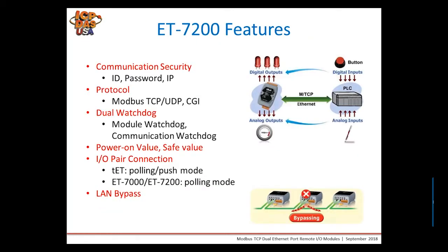This reduces the number of Ethernet ports required and Ethernet switches. So in this configuration on the bottom, the PLC or controller connects to one port of Ethernet switch, and a single port is used for the slave devices, which are daisy chained onto each other. Versus the top configuration where each individual slave device and master device must have its own Ethernet port, and because this illustration shows that you need more Ethernet ports, you have to connect an additional switch as well.